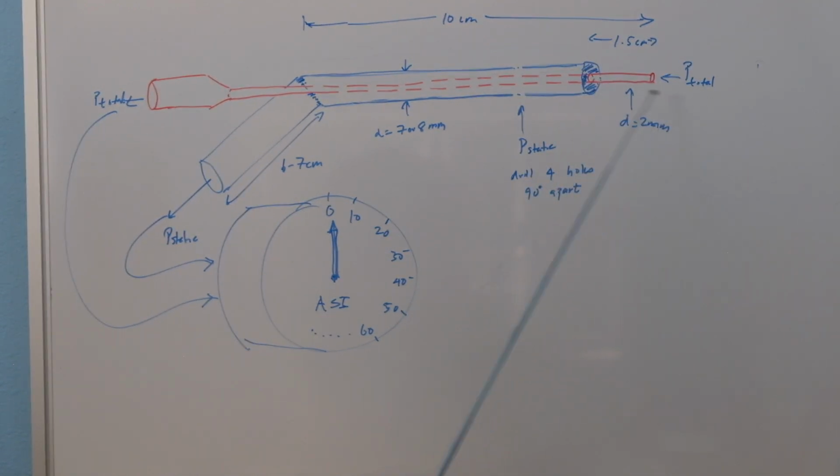You don't want any air coming into this static portion over here from the front. That will decrease your reading. You want this to be absolutely still air as far as possible. One thing people do is to make some kind of a shape to make this a gradual slope over here. I think that might affect some of the turbulence around this area, but I haven't done that yet, but I'll maybe do that later. You can put in some plastic or epoxy and just make a triangular shape to smoothen out this edge over here.